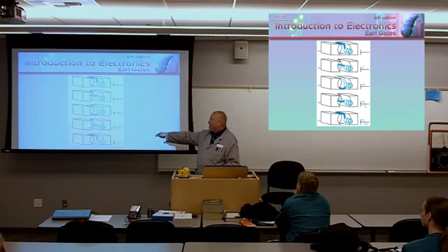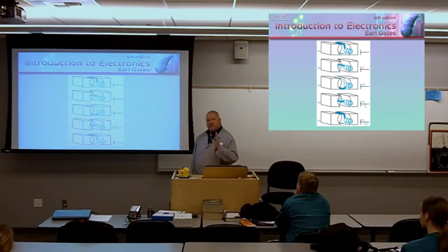I rotate it another 90 degrees. Now I'm coming up on the back side, 270. Parallel or perpendicular? Perpendicular. What am I going to do? Generating, Faraday's law, maximum, cutting my maximum field. I'm right here. I complete that cycle. I've just created 360 degrees of a sinusoidal waveform. This is an AC generator.